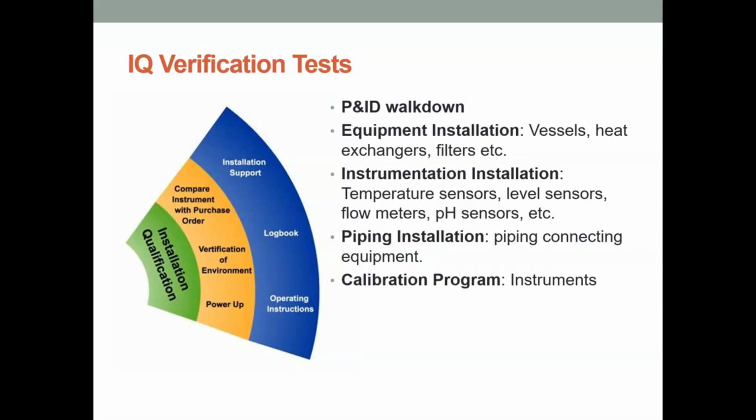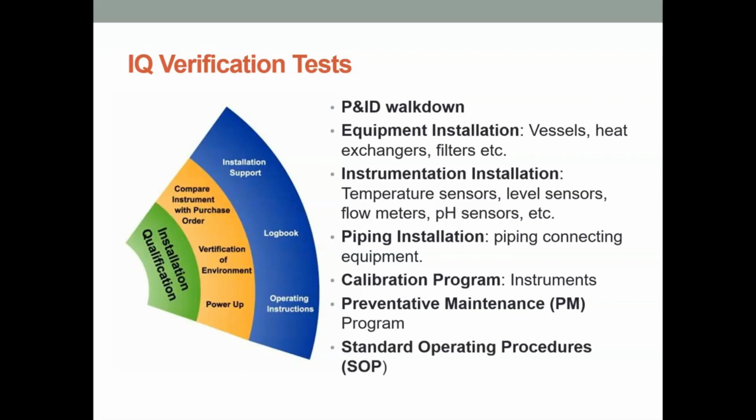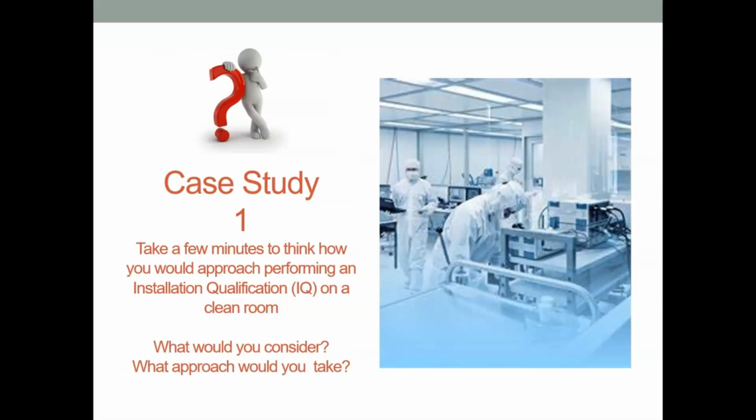The calibration program for our instruments, has that been put in place? Do we know what calibrations are necessary? And the preventative maintenance program, what parts are we going to be needing to change out? With what frequency will we be needing to change them? How regularly do we need to be inspecting each of the components of the piece of equipment? Is there a standard operating procedure in place for operating this piece of equipment or this process? And has it been reviewed and approved, and is it controlled?